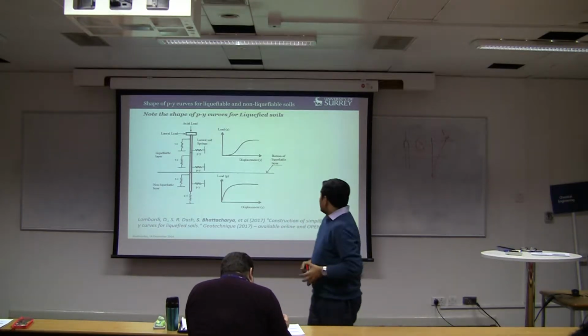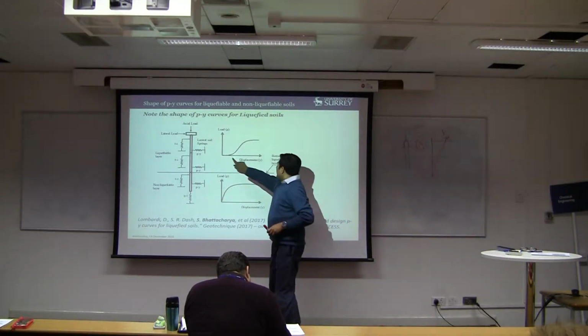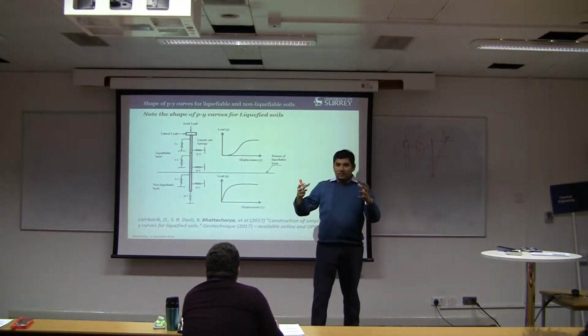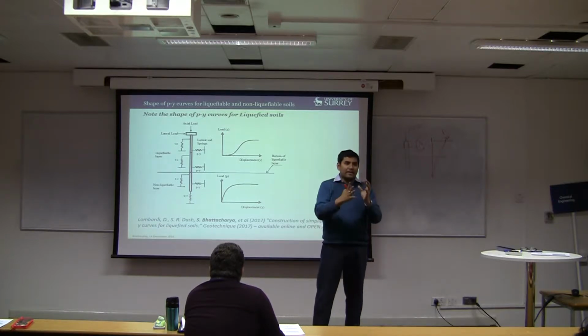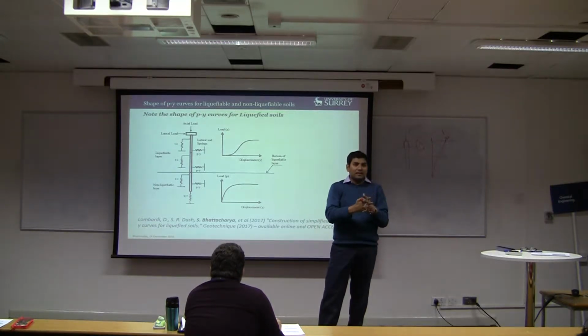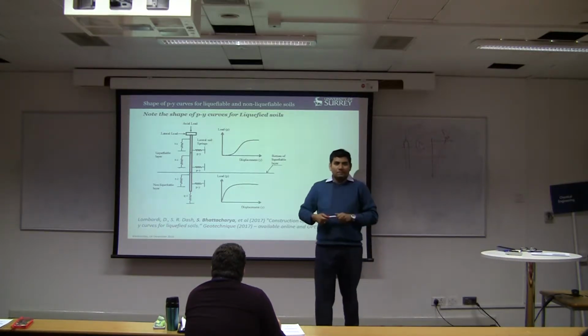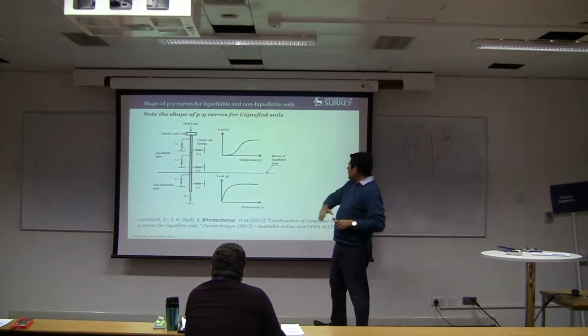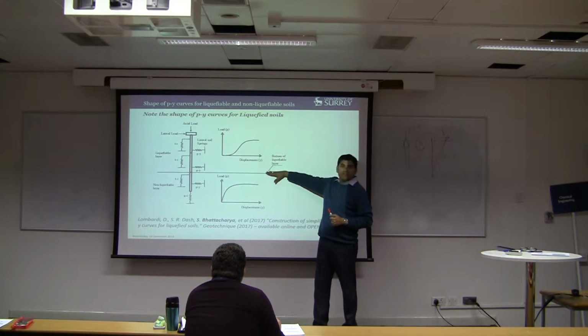Yeah. So this point is, if the pile is pushing into liquefied soil, right? So at a certain movement, we start to see that it is also giving resistance. At that point, the liquefied soil gets locked in and gives resistance. Yeah? So when you do a model, first thing is find out to what depth it will liquefy.